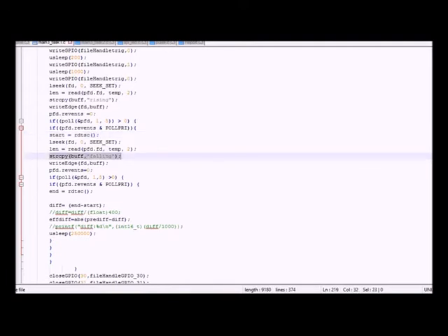When you poll on falling edge, it generates an interrupt, and then you know that the echo has ended. So you get the end RDTSC, and then you get the difference between the start and the end RDTSC, and use the velocity of sound in air to get the distance between the obstacle and the sensor.